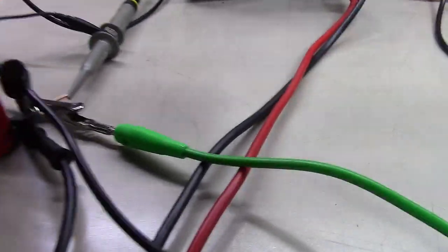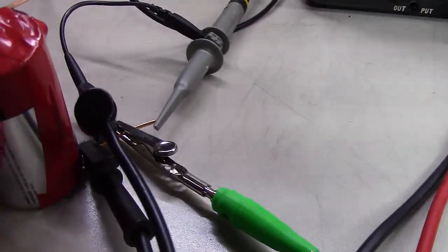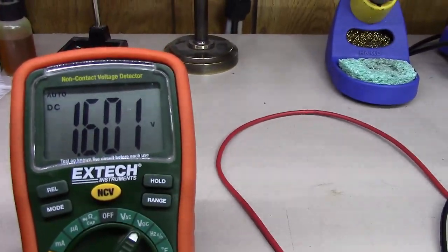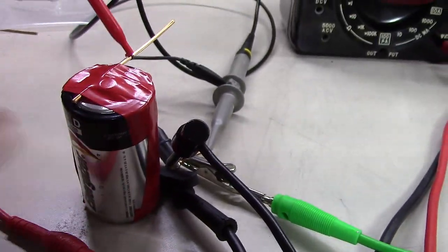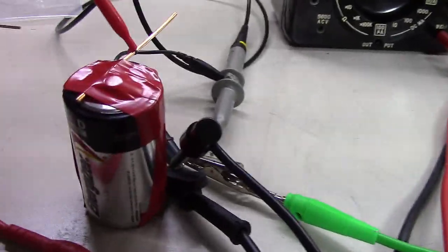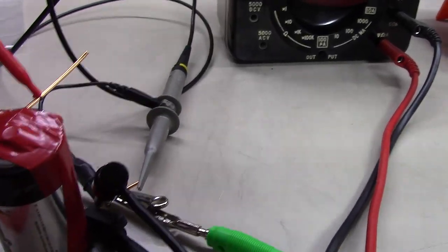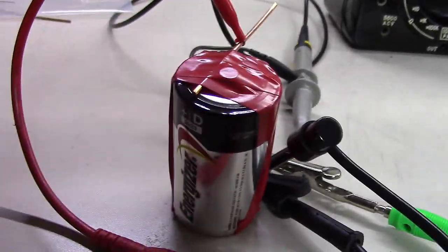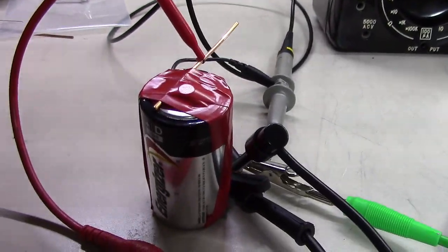But if we grab this test lead here and drop it onto this end of the battery, if you'll notice over here, what do we get? Oh, it says 1.601 volts. Well, guess what? Even though they say they're 1.5 volts, they can range anywhere from 1.6 maybe down to 1.4 volts. It just means a good new battery should be at least 1.5 volts. Sometimes they have a little more oomph than that, and that's okay. Most of the devices they connect into are well aware of that. So this device is putting out 1.6 volts right now.